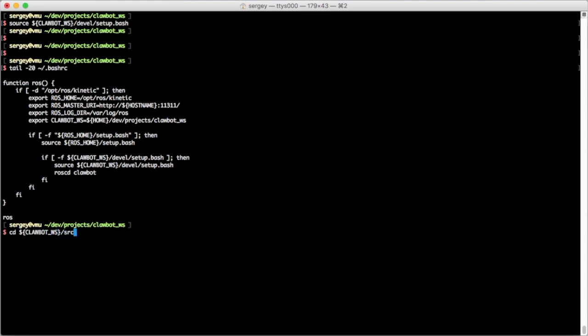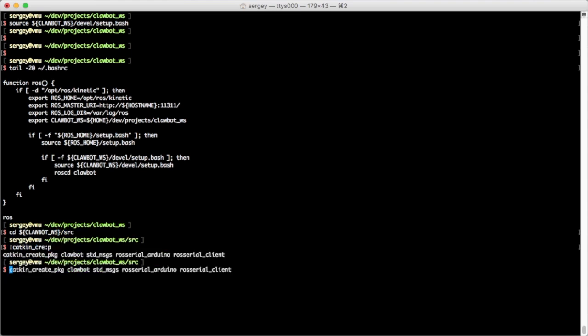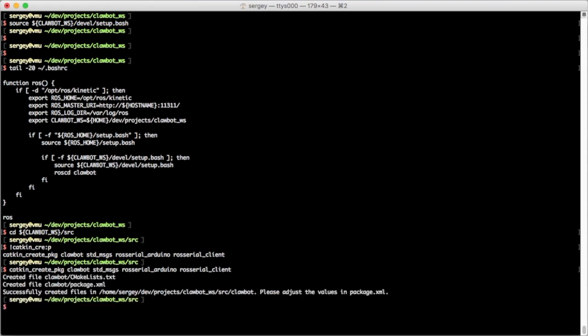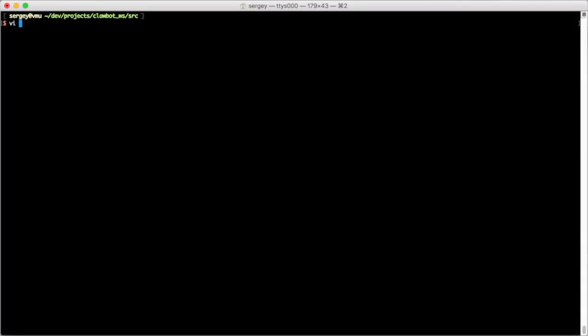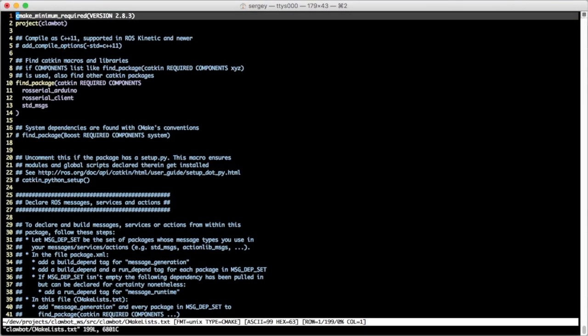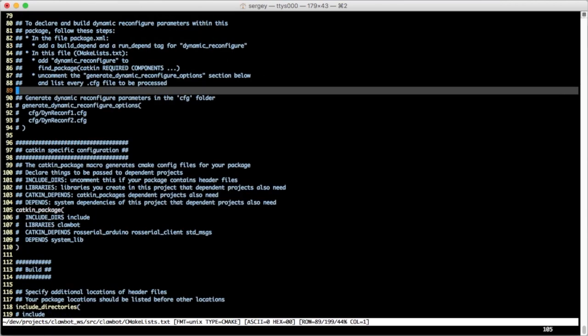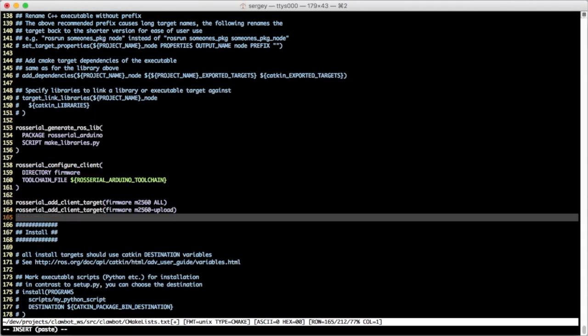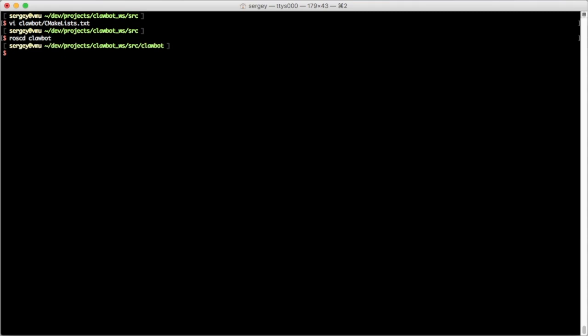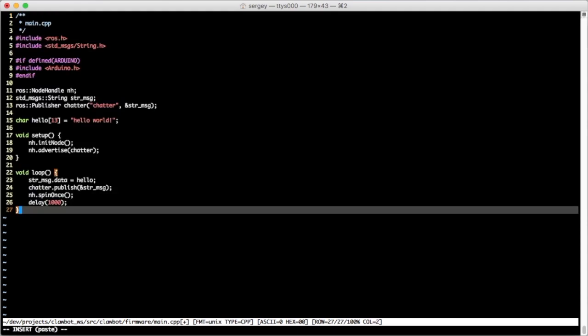Of course, the package has to exist first, so now I go ahead and create the package. The tutorial on the ROS Wiki instructs to replace the content of CMakeLists.txt with their example. Instead, I will keep the auto-generated code for later modifications. For now, I just add the required macros. I use M2560 for the target name, because it's easier to see what firmware I'm building for. Create a directory firmware and write the following CMakeLists file into it. Also add the following main.cpp file into the same directory.